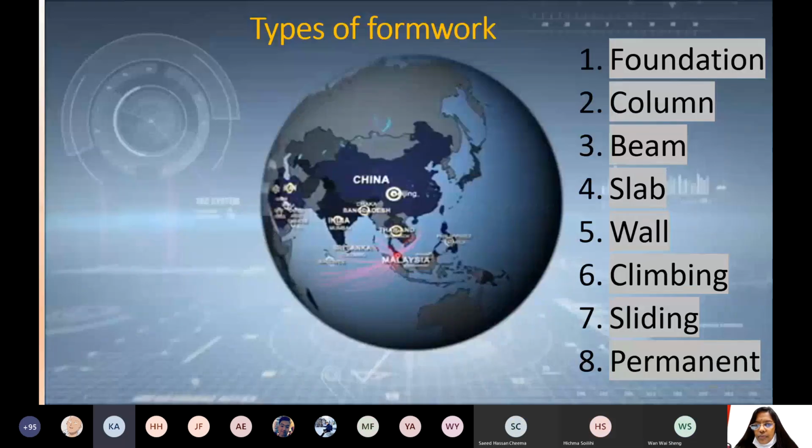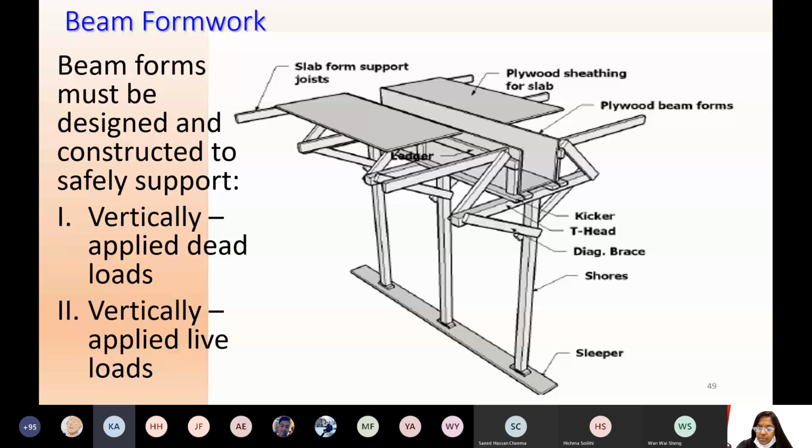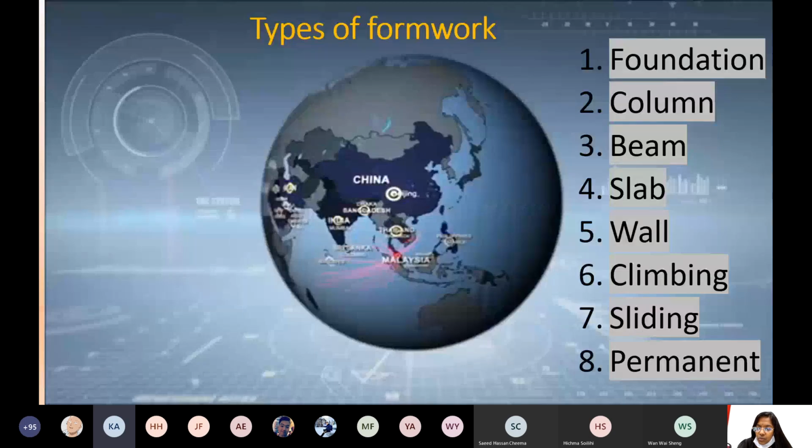Types of formwork. Is there any other question? He asked me the difference between scaffolding and formwork, and I will show you later with the members also. But formwork is the one which is forming the beam or column or the slab which you're going to construct. The member that is going to support, a pole-like structure, is called scaffolding. Mainly it is meant for that. Later we will see the member, the diameter of the scaffolding and the spacing, all those things. I will give a glance only in this chapter because it's also important. Later we will have the exclusive chapter on scaffolding.